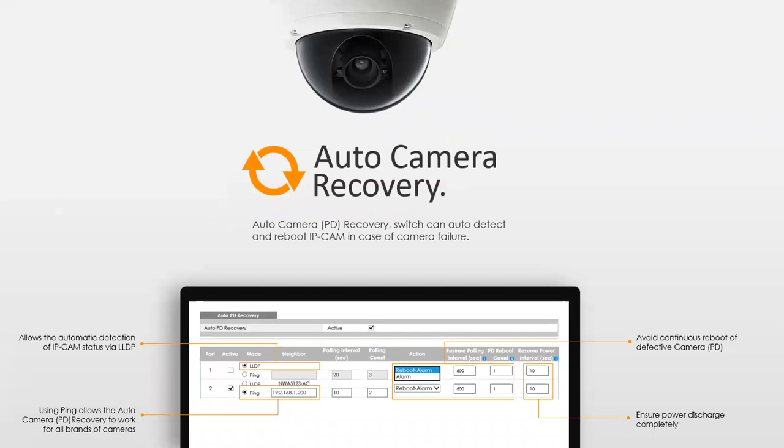We also have an automatic camera recovery mode, and again, it doesn't actually have to be used just on cameras. It will work with APs and other PoE devices. So basically, you can use either ping or LLDP to monitor the device. You define how often it polls this device, and if it fails, how many failures before you power cycle the device. So it'll automatically power cycle the device. And you define here how long it waits before it resumes again to give that device time to boot back up. So it's really handy for making sure connected devices are always online and responding.